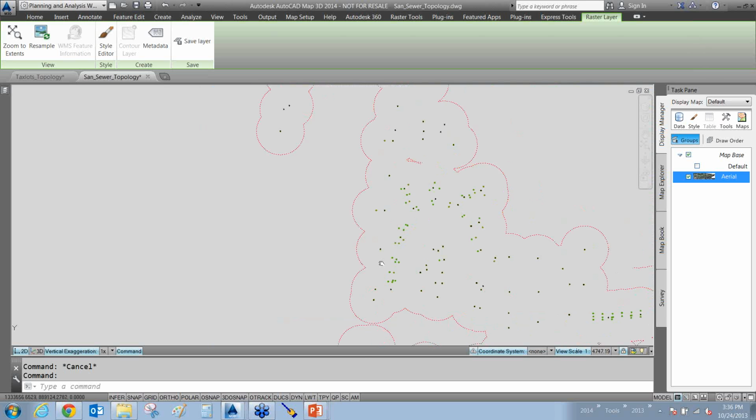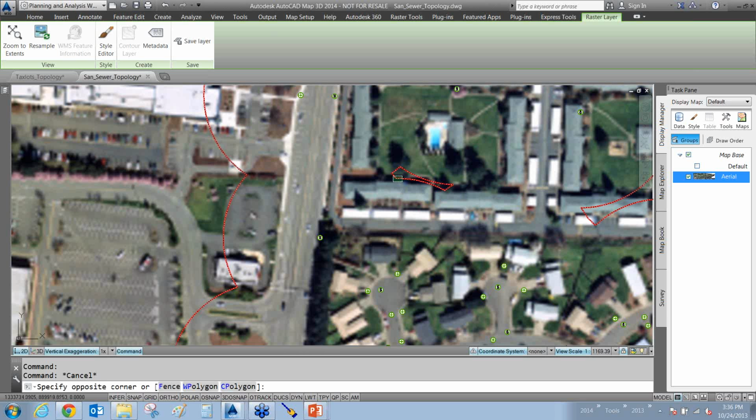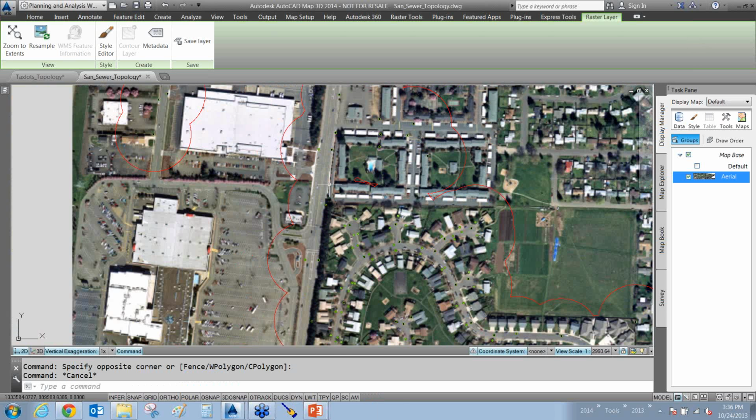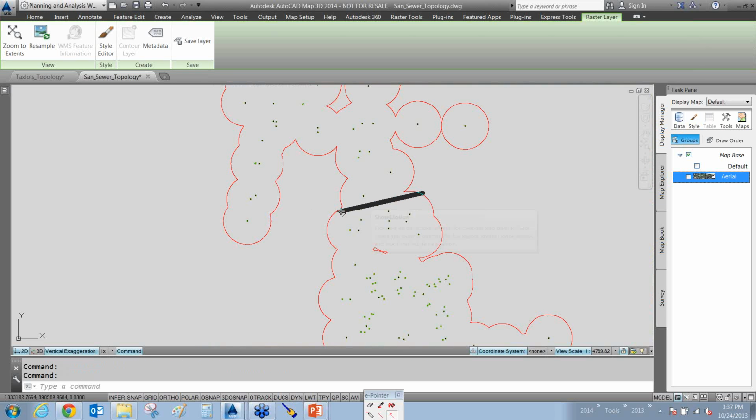So this is a polyline, and I can use that to hatch with, but I can see areas in here, like this guy right here, of, oh my goodness, I don't have any coverage right there, and I may have to pay attention to this. That building that we were going to rip out a little while ago. Okay, notice no coverage in that area, so I better add in some extra fire hydrants.